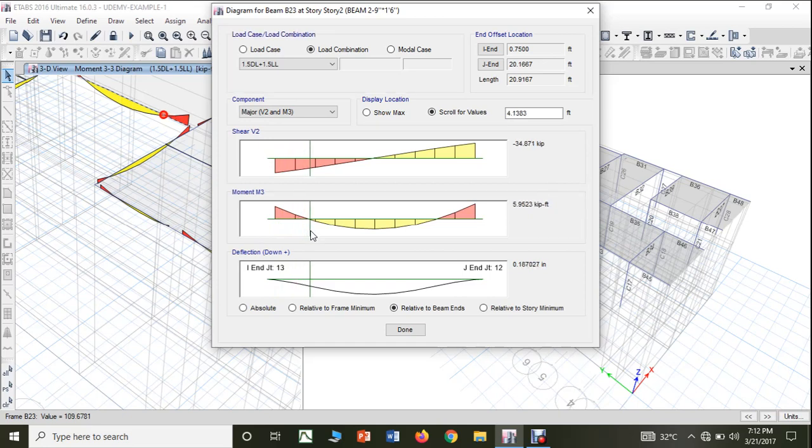Like this you can go, it becomes 0. So after the negative bending moment, you come to the positive bending moment at the center of 114, and again it becomes 0, then it goes to the final 168. You can see here it is 168 at this support and 139 at this support. Out of this, since you want the maximum, the maximum is 168.